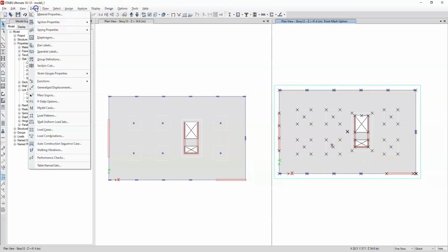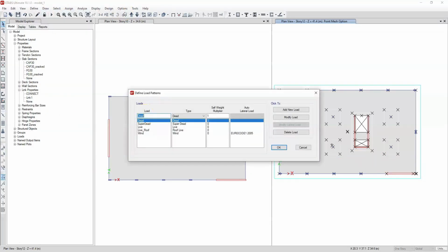The next step is to create the load cases and apply the forces so that we can measure the stiffnesses of each story in terms of directions. Two orthogonal flexural directions and one torsional direction. We are going to create a load pattern called Fx, another called Fy, and another one called M, to apply a horizontal force in two directions and a torsional force.